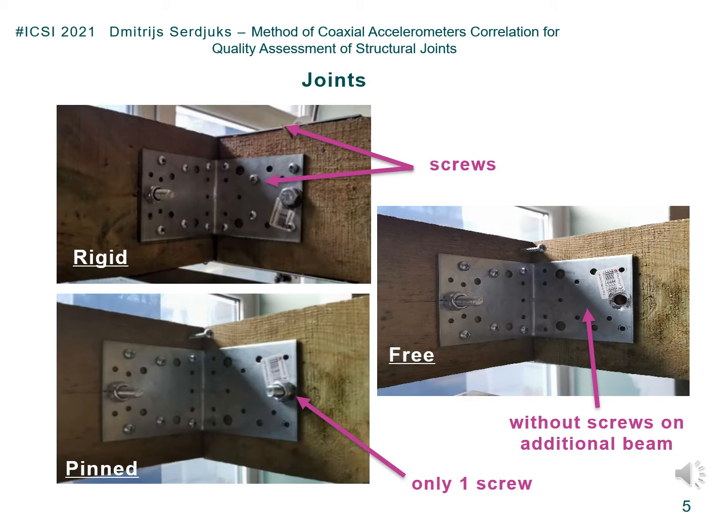Three statical schemes of the timber beam stand were considered with different types of joints of main and additional beams. Rigid, pinned, and free joints were used to consider probable stages of the joint's degradation and were obtained by removing the separate fasteners, screws, and joining steel plates.